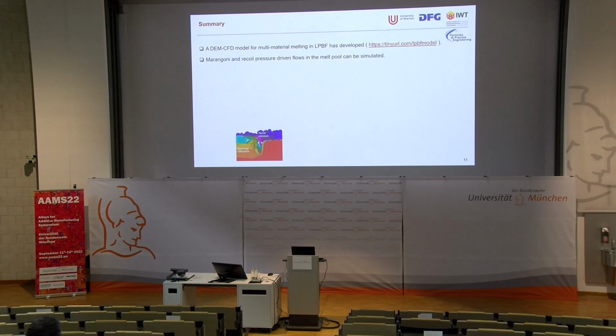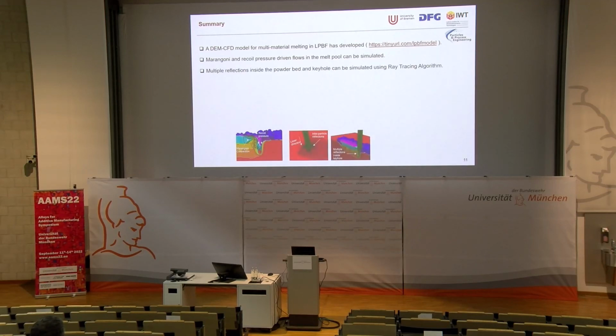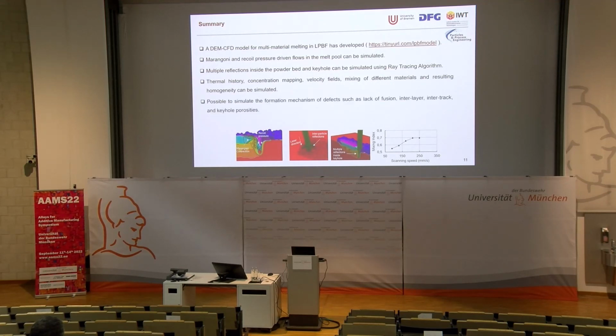With this, I would like to conclude my talk. We have developed a model for multi-material LPBF. You can download this model using this URL if you are interested, and the model can take into account the effects of Marangoni and recoil pressure and fluid flows. You can simulate multiple reflections inside the powder bed and inside the keyhole using the ray tracing algorithm. You can see the track inhomogeneity, and we can also simulate defects like lack of fusion and keyhole porosities using this model.